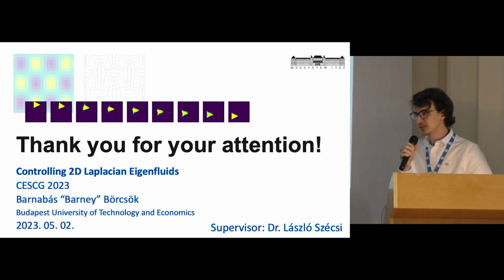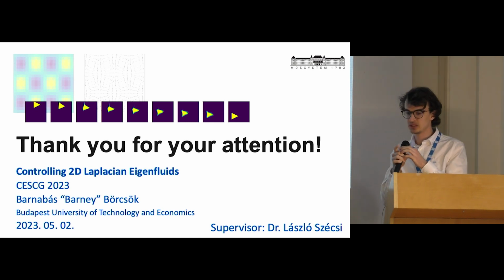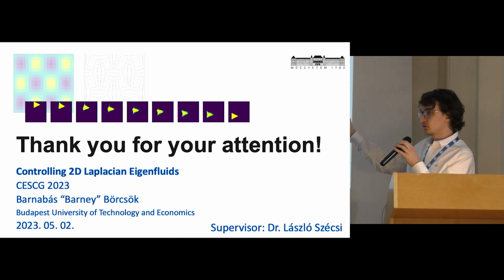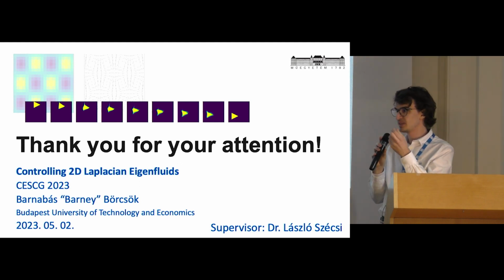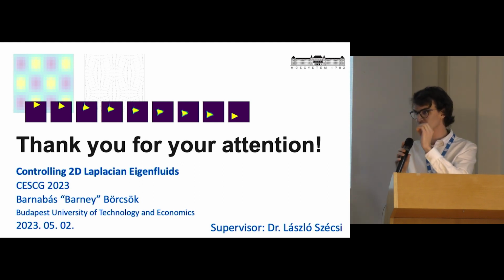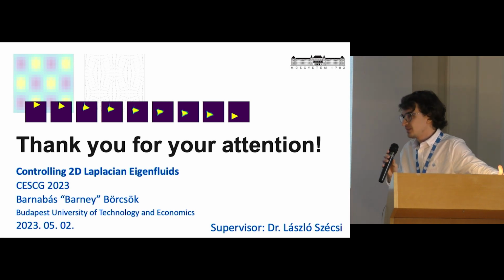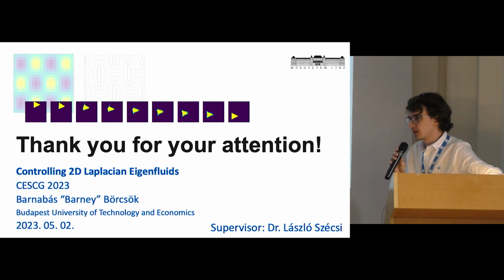So this is a really interesting question, and the simple answer is that we can use however many basis functions, because actually the error that we acquire in this reduced dimensional simulation is very well defined, because simply we can't simulate smaller vortices than the smallest vortex that we use. So it just depends on how well you would like to be able to reconstruct your velocity grid.